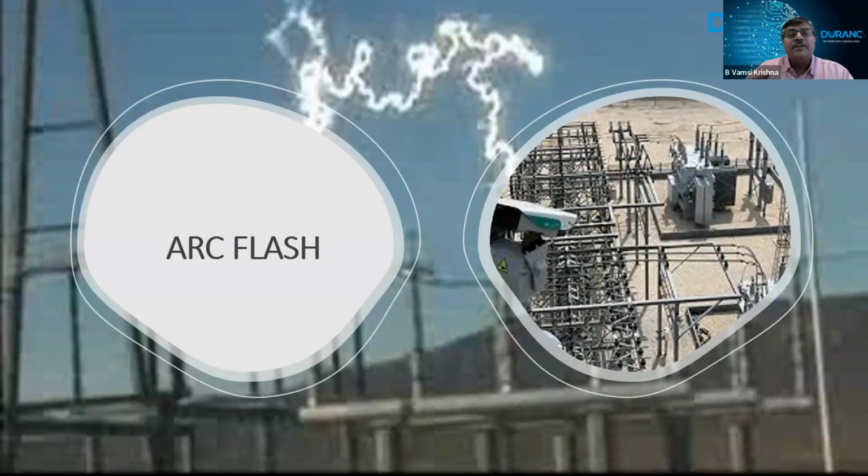These actions can also be taken immediately in an automated way through relay integrations. When the event is detected, it is sent out to the relay device, which can take up these actions of de-energizing the circuit or activating the fire suppression. This proactive approach helps prevent arc flashes from escalating into a major fire, reducing the risk of damage to equipment, injuries, and potential downtime.